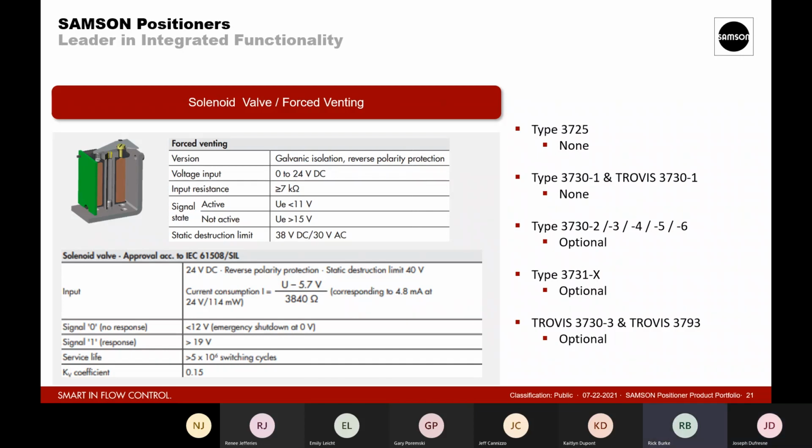Yeah, and so with solenoid valves, the important thing is to know that it's there or not. I had a problem one time, somebody had sent out one of our valves to get repaired in an outside shop. They thought that the positioner was bad, so they changed it. They bought a positioner from us, but they didn't specify that it had an internal solenoid valve, and they couldn't get it to calibrate.